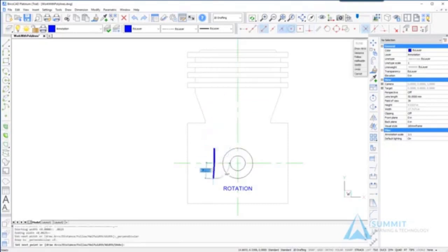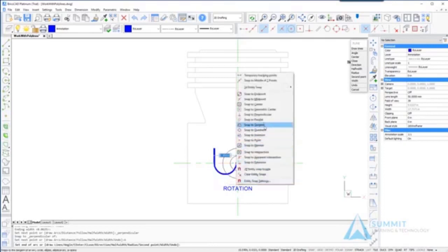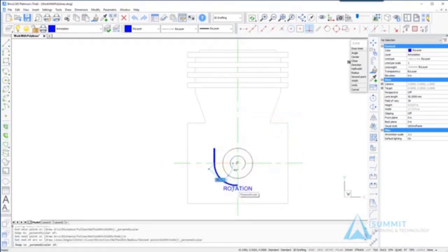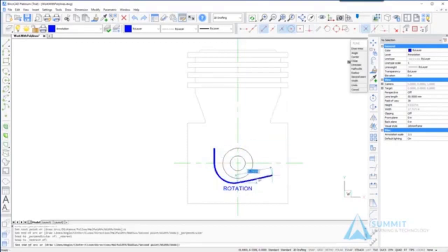The next thing that we want to do is change the mode to arcs, and now as we drag the cursor we're drawing an arc. So we want to try and position the arc generally concentric to that circle, and selecting a point there, actually nearest, and then switching back to draw lines.